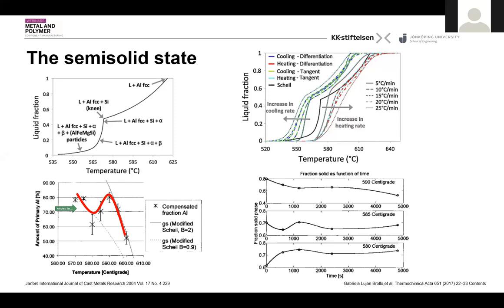This is also quite important in heating because, depending on how high in temperature you go, you can see an evolution with time where you get a certain fraction at the melting point, and then you can have a melting sequence, or you can have, at a slightly lower temperature, a resolidification sequence, depending on whether or not you are to the left or right on this S-shaped curve here to the left in the picture.